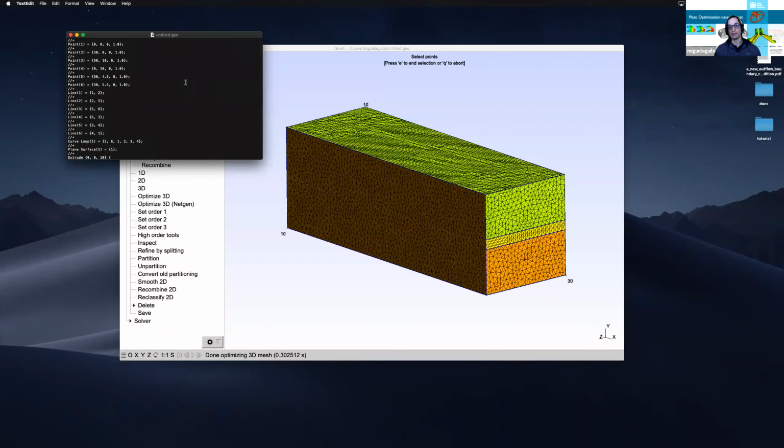Another way to do this and change the mesh is by coming here, and this is X. So if you see the points, this is basically X, Y, Z, and then this is the element size right here. By default, it sets the element size to 1 unit. You can also come here, and then let's say now we're going to change that to 0.4.